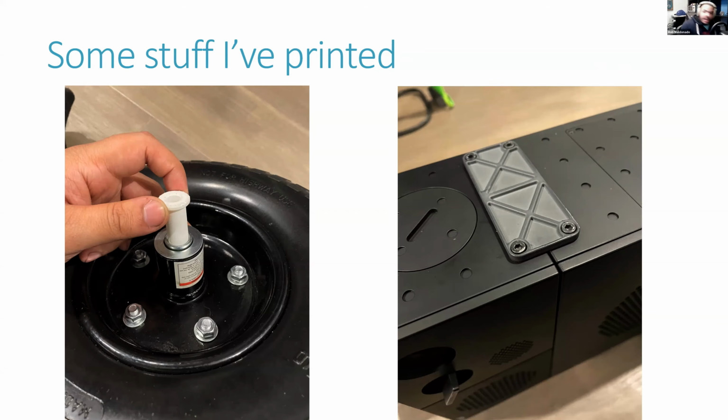So in order to get a properly fitting part, I've learned a lot of things over the years using different sorts of 3D printers. A source of error can come from your measurement device, though it's typically pretty little. Another is from what your printer can handle. It'll have a certain tolerance range that it can handle. And another is how you save out your SolidWorks part as STLs.